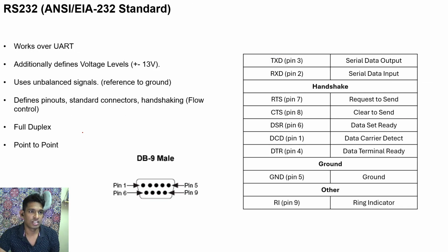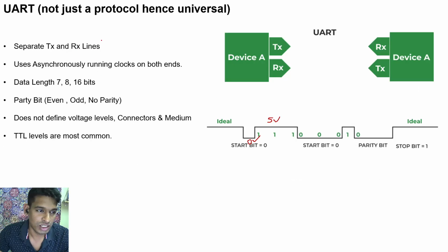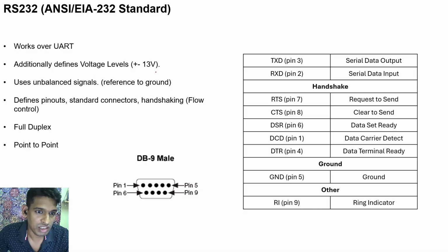Moving on to RS-232. Now RS-232 is not a protocol. It does not define the logical constructs for sending and receiving data. It only defines the physical aspects. RS-232 works over UART, which means the data is sent fundamentally the same as UART, and in addition, you are defining the voltage level.